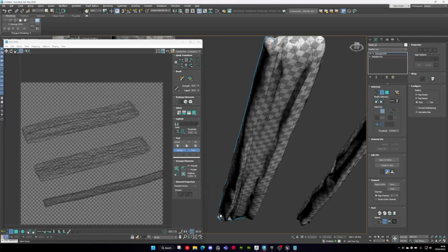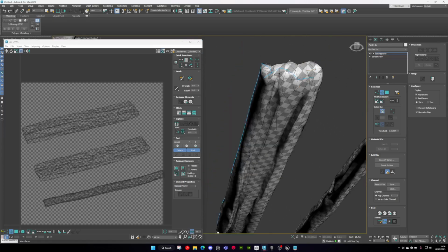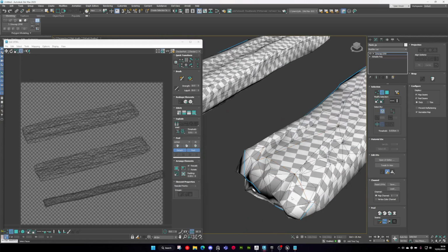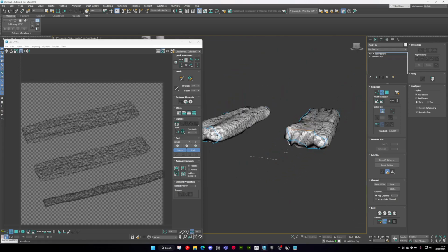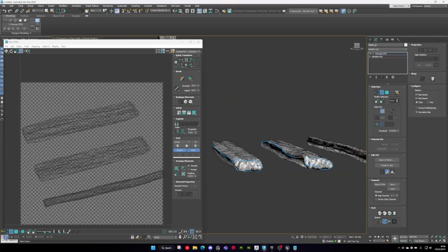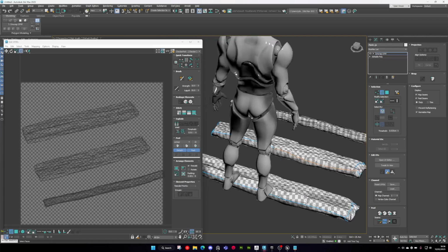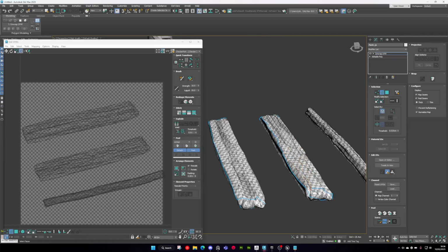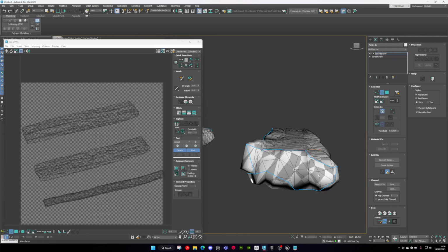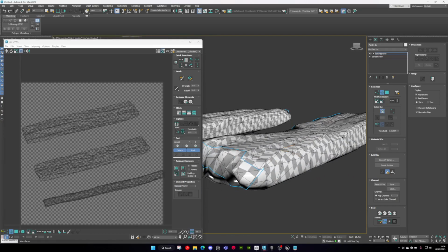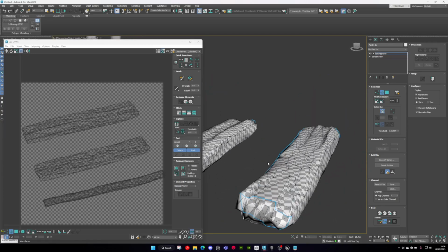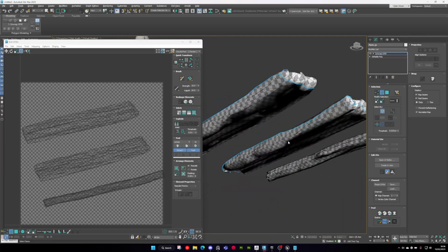These are going to be pretty awful UVs just from the way that I'm really rushing this, but it will be enough to get the point across. I would ideally try and have these in 3 different islands, so you have the end caps and then one long unfolded bit, just because I'm not going to have any hard edges in this because it's such an organic shape. And I'm just going to chuck face weighted normals on it to get better shading.